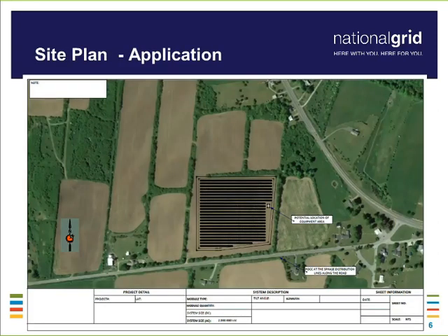Now to kind of just step you through all those site applications, this would be typical for a site application for when the customer had made his application. Very basic, shows the array, some streets, some basic information, the potential point of common coupling, and where the customer's equipment is going to be. It's also important to note that within the title block, we should be putting the customer's name, and that's the name that is actually on our CSS billing account, and also the site address. So in case this document does get lost, we can easily figure out where it belongs.